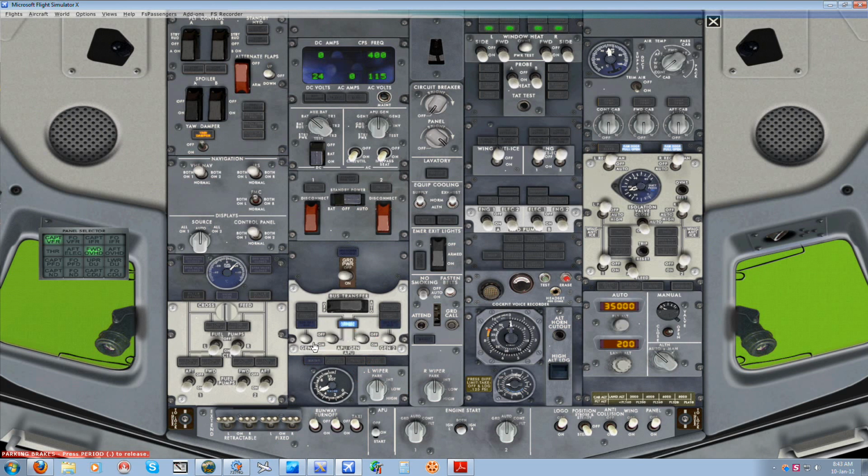You can't actually have the engine generators running as well as the APU generators running. You can only have one or the other. So what it does, it actually closes that circuit. It actually turns off the APU generator, and the light becomes available.